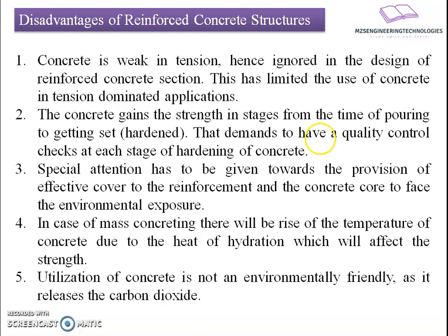It requires special attention towards the environmental impact, as we are going to use reinforcing bar. When they are subjected to environmental exposure, they are subjected to deterioration and corrosion. So we have to take special care for the effective covers, and that has made a limitation towards the application of this section in severe exposures.